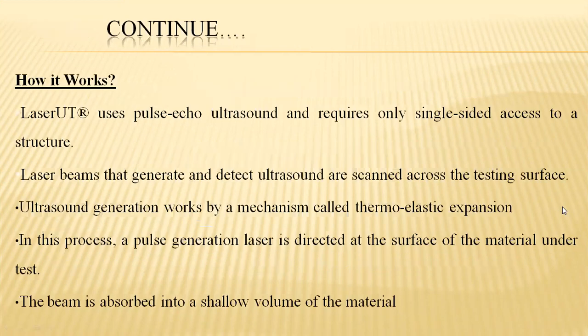Composite materials in aircraft can be dissected very clearly by utilizing this technology. It uses pulse echo ultrasound, made easy to process, to penetrate into the materials with the help of laser beams that generate these ultrasounds, and it is scanned across the testing surface.